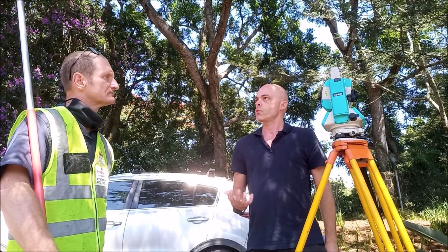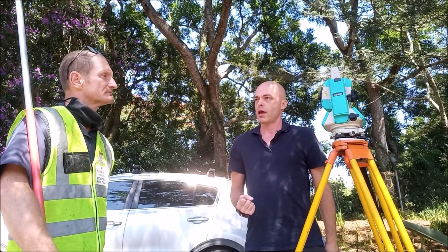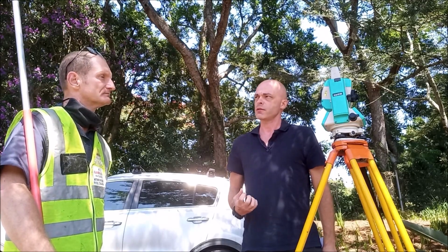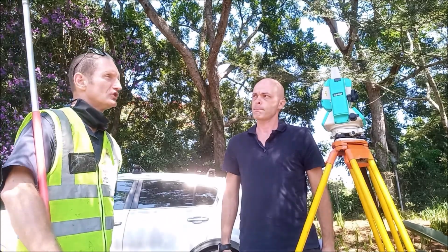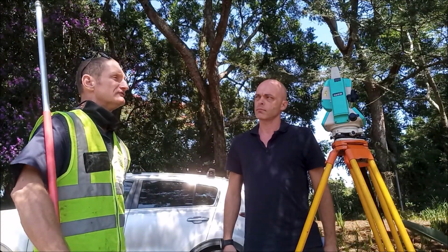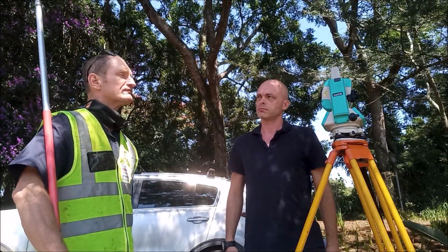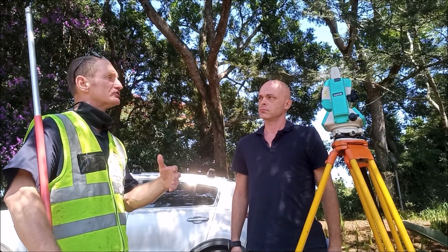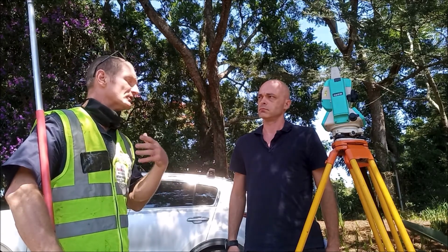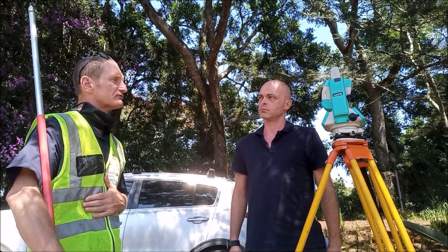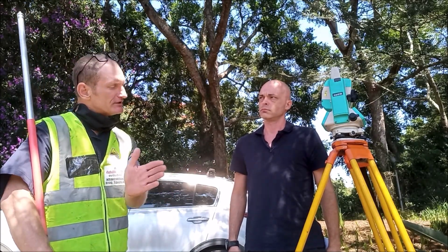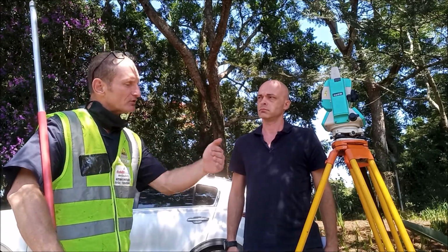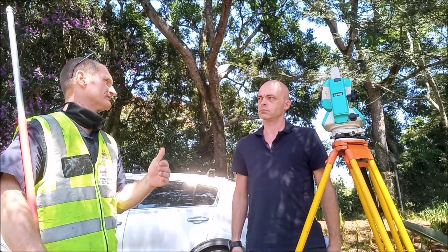But when it comes to corner weight scales and having to measure the weight of the vehicle, why is it important to know the center of mass of the vehicle? So in the investigation of any accident, you may, for instance, be dealing with the rollover of a vehicle. Now, in order to calculate factors of rollover, you would need to know the lateral position of the center of mass, the height of the center of mass, or the fore and aft positioning of the center of mass.